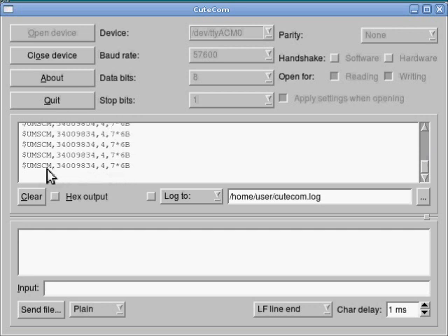And these messages are data messages from utility meters that are being picked up off of the air. This is a standard consumption message, SCM. And inside of an SCM message, there's a lot of data, but the key things here that we care about are this first field, which is the serial number of the utility meter transmitter.